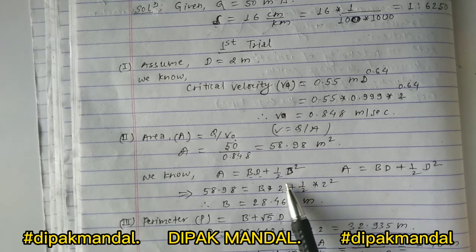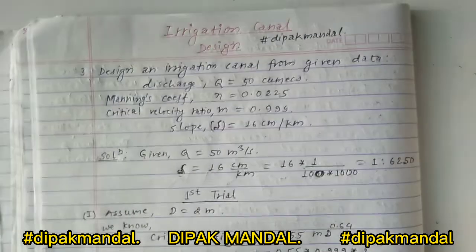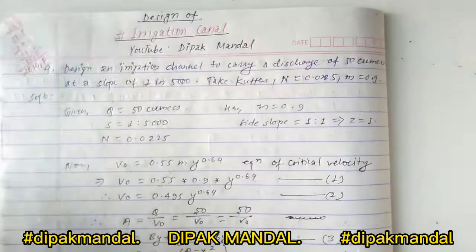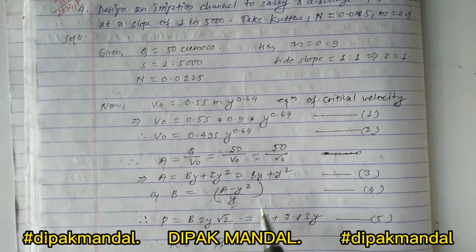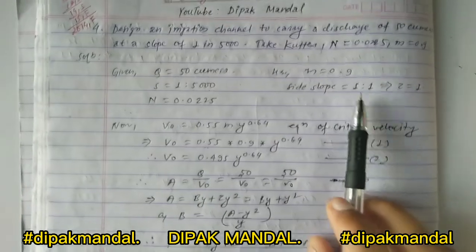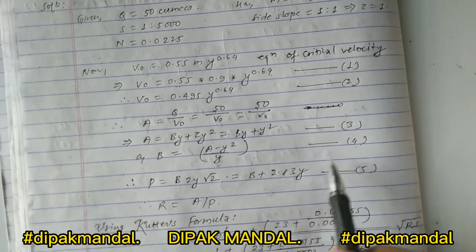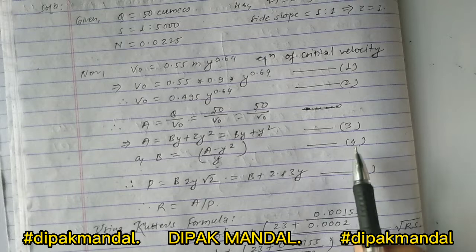It depends on the slope. Whenever the slope is 1/2, we have to take 1/2, and whenever the slope is 1:1, then we have to take the value of z equal to 1, as in this numerical. Generally we prefer side slope equal to 1:1, so we take this value, and after solving this we get equation number 4.